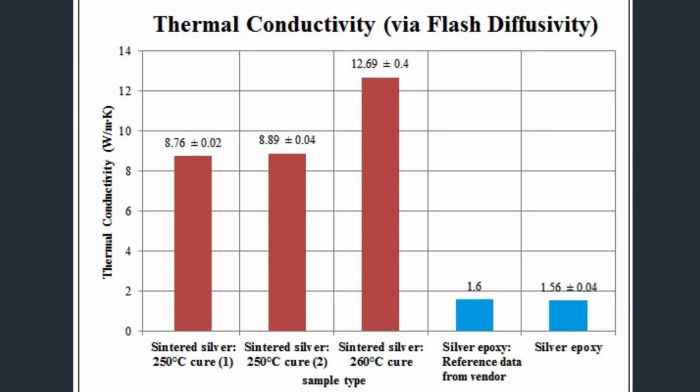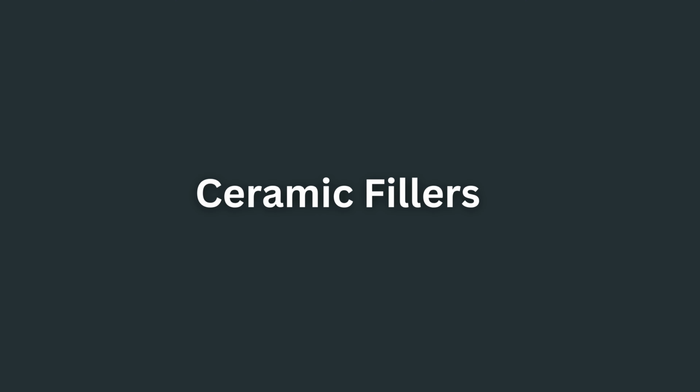In electronic packaging applications, silver nanoparticles dispersed in epoxy matrices form efficient heat-conducting networks that can achieve thermal conductivities approximately twice those of unfilled epoxy systems. However, the high cost of silver restricts its use to specialized high-performance applications.